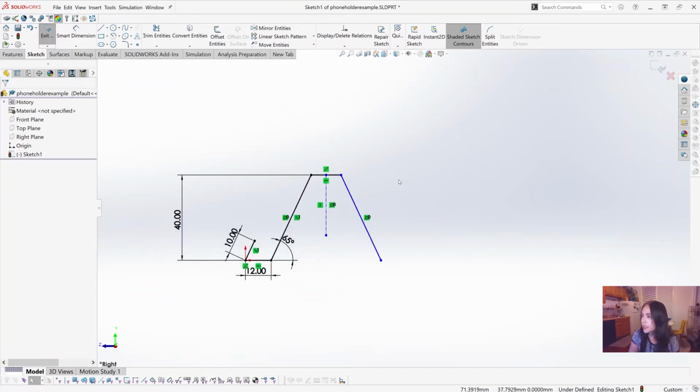And just for example, I want to show what the phone is going to look like in this. So what I'm going to do is create construction geometry. Again, remember, this is just reference geometry to show what that phone will look like. So I'm clicking here and clicking this rectangle drop down. In the drop down menu, there's a bunch of different rectangle options. These rectangles here are straight up left and right, so horizontal and up and down lines.